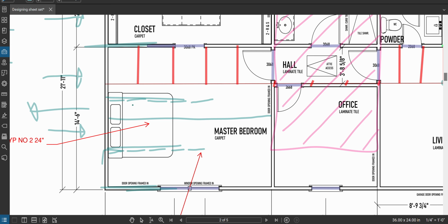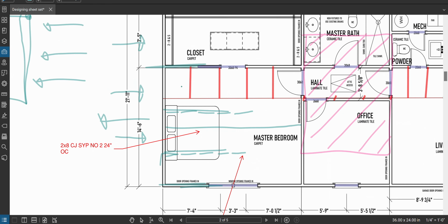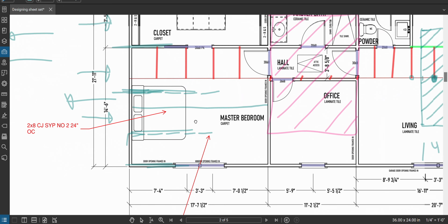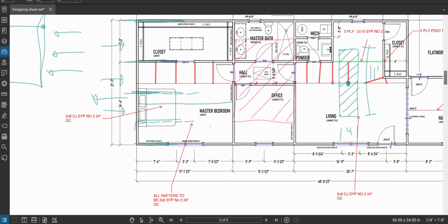So by putting these blocks in and then tying them all together with a 2x4 on top of all the blocks, I'm gaining stiffness. It's like I have a wall here. It's like I have stiffness added to my wall so that the wind can't blow my wall in, right? So I'm going to do those tricks when I need to, but that is something that needs to be done.